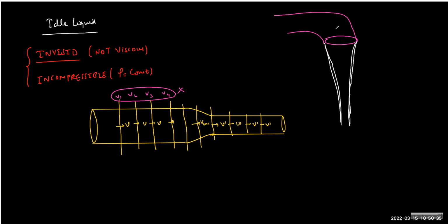Because the amount of water you are giving is fixed. So you are giving, let's say, maybe 1 liter per minute as the rate of water coming out of the tap. Now, as it falls down, the velocity will be more. So this is V2, and because it's a free fall, V2 squared equals V1 squared plus 2gh. Let's say h is the height. That we will also prove in another way.